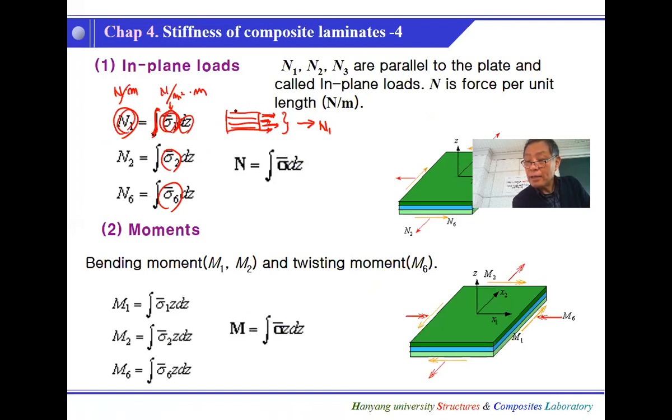But the reason is that if we consider this width or length, then we multiply by length, then we will get total load N. But this in-plane load is defined as Newton per length. Okay, Newton per length. So we integrate only through the thickness. Stress times thickness.